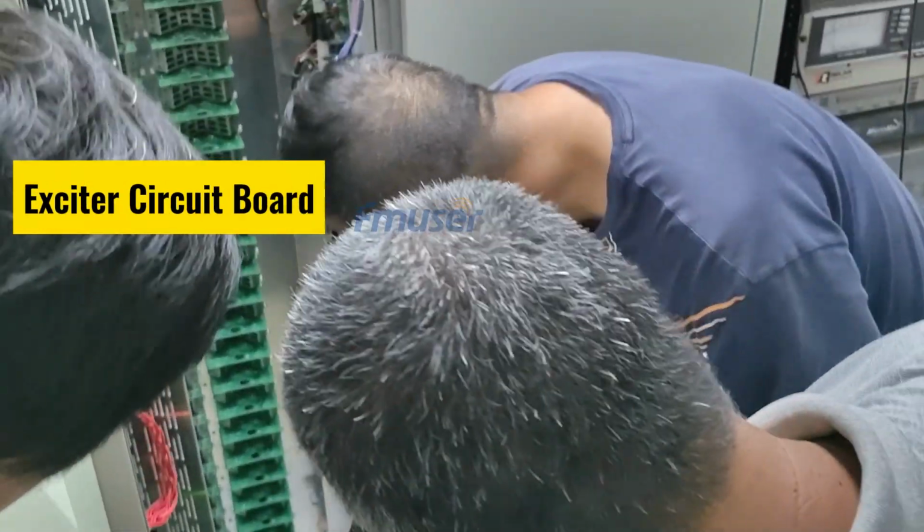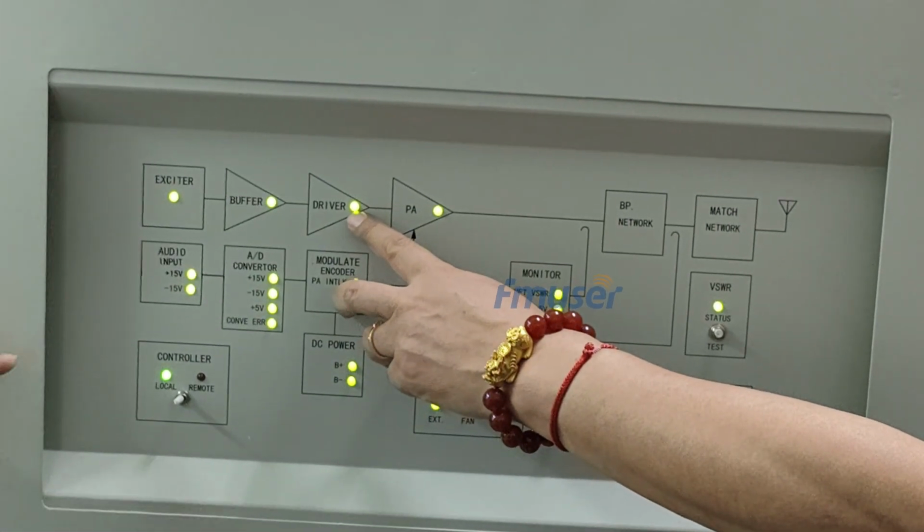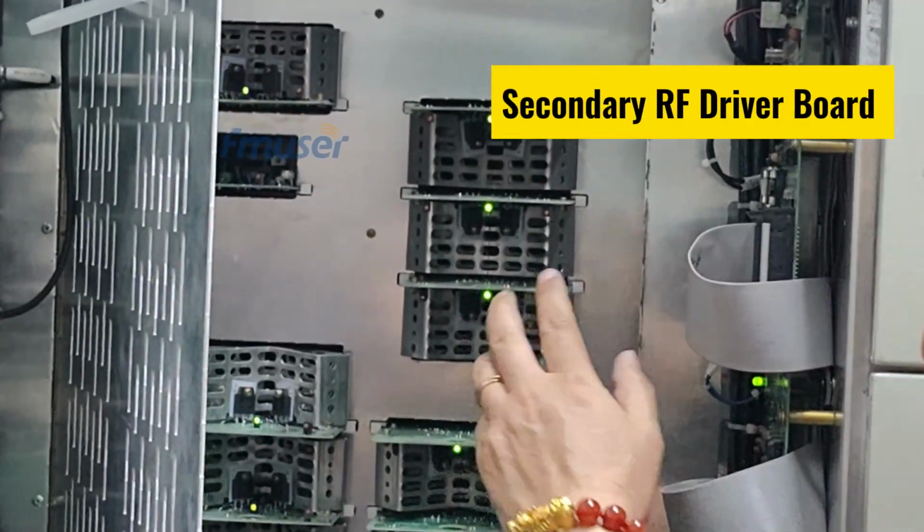In the lower right corner, you will find the exciter circuit board, corresponding to the exciter indicator light. On the left side of the top layer, locate 2 circuit boards. The one on the first layer is the level RF driver board associated with the driver indicator light. Adjacent to the level RF driver board are 3 secondary RF driver boards on the right, corresponding to the driver indicator light. On the left side of the second layer, you will find the buffer amplifier board, which corresponds to the buffer indicator light. Finally, the circuit board with the largest number is the power amplifier board, associated with the PA indicator light.